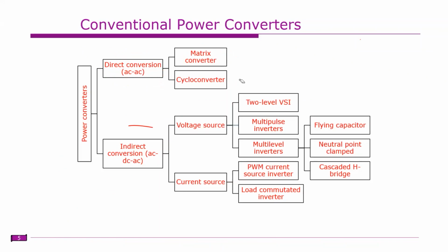So there are disadvantages with this one. With cycloconverters, you cannot control a huge range of frequencies, especially when you are operating with high-speed electric drives, for example. So these cycloconverters are not preferred. When you are operating with low-speed drives, maybe in the 100 RPM, 200 RPM, 300 RPM range, in that case the cycloconverters may be suitable.